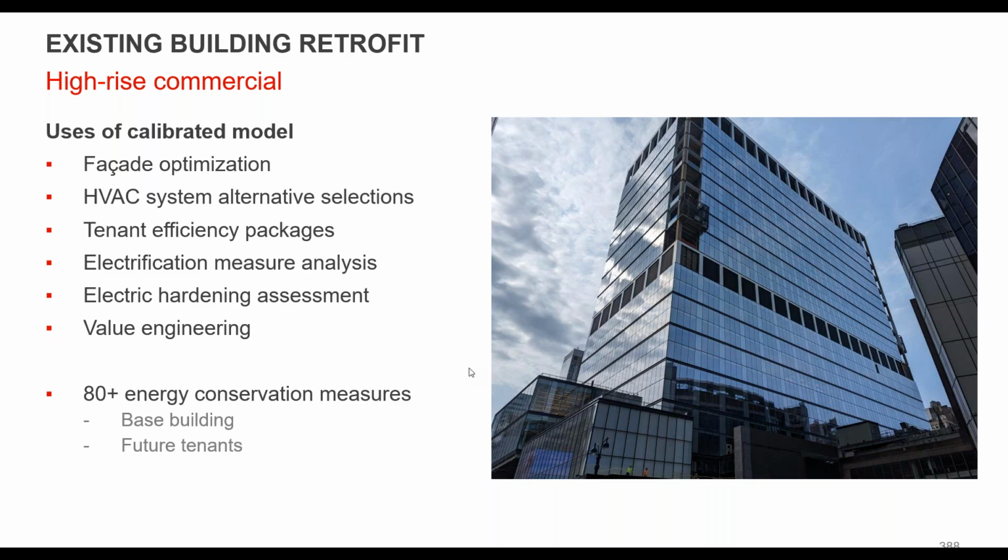And they went from a double pane specification to a triple pane specification because of the model. The model proved out that it would pay for itself in less than 4 years. So to add an extra pane structure was okay, so they were able to add that. It helped with choice of HVAC system. They were looking to replace in kind, but we ended up with ventilation being separated and adding DOAS units and a full fan coil replacement of all the perimeter induction units. So that was something else that came out of the model. We were able to test all these different options.